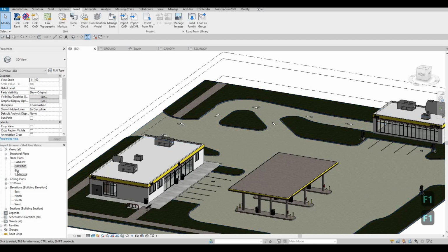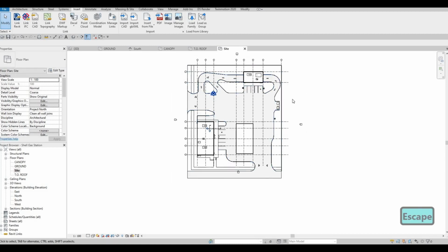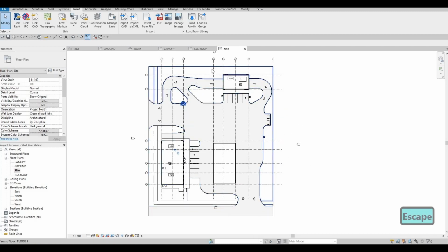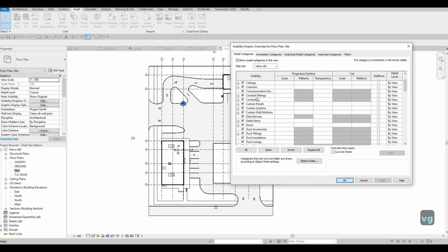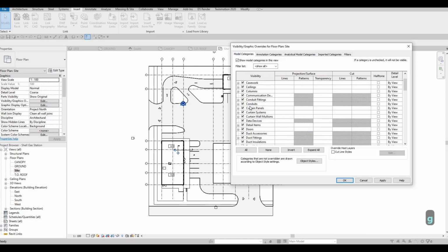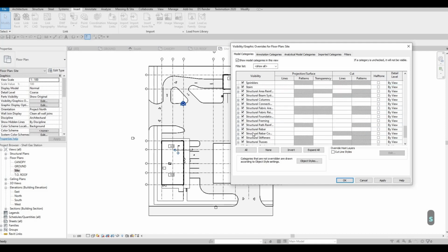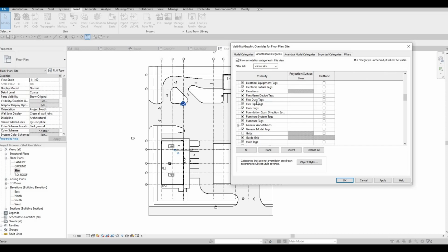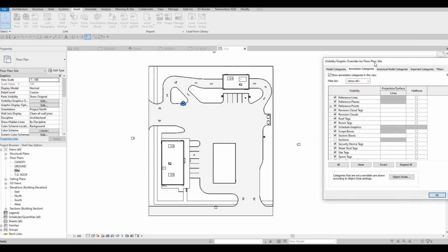What I want to do now is to clean up the site. So in site plan, most of the time you remove all of this. So VG, not remove, but hide it. So we hide the grid line. So G here, uncheck this one. In model section, we need to remove as well or hide. So I'm gonna put section right here. S, uncheck that one. Apply, and then anything else that we could